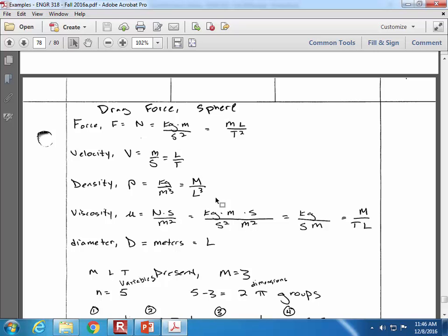So I'm trying to simplify the units. And as I do that, as I'm simplifying the units, I'm creating these groupings of variables. All right, I can cancel out the length parameter here on the density term. And what I'm going to do for that is I have density, and if I multiply it by diameter cubed, then that'll cancel out the length to the 3rd power, and all I'm left with is units of mass in that grouping.